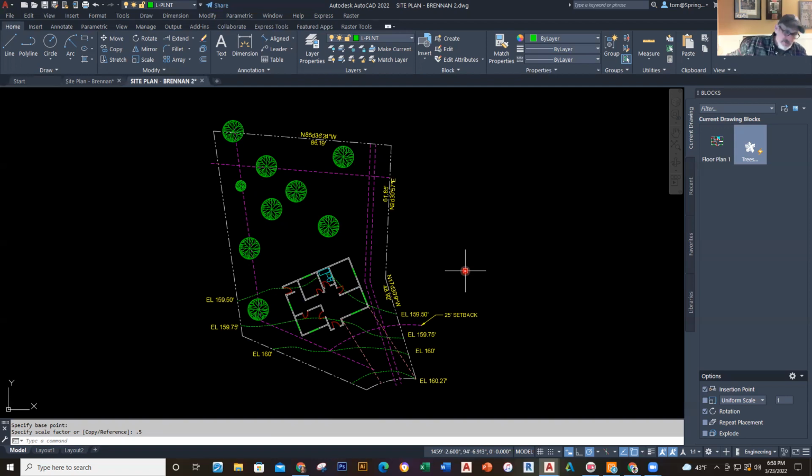Again, the beauty of this one is that you're going to learn how to actually put in degrees, minutes, and seconds. That's a big deal. You're also going to know what that's doing and whether it's right or not when you go through it. Remember, what I did is I used the @ symbol. I typed in the feet, in decimal feet, and after that I typed in the actual bearing, starting with north or south. Then you put in the degrees, the minutes, and the seconds. That's how you do that.